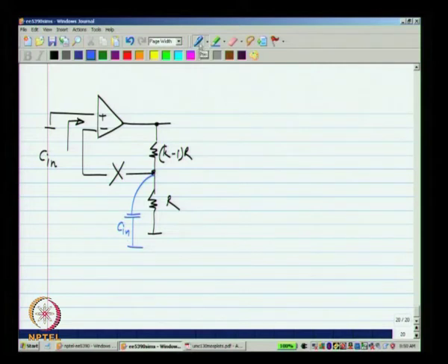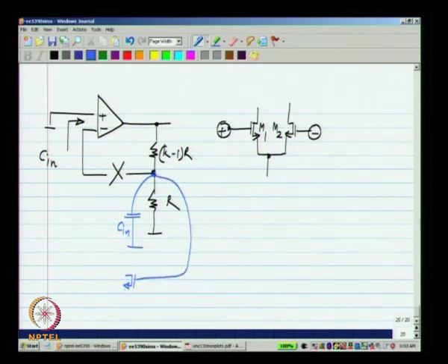Okay. What can be done, for instance, is that let us say this is a conventional op amp with a differential pair M1 and M2 which are identical. What you can do to mimic the loading approximately is simply connect M2, okay, that is to this node you connect M2 and leave it there.